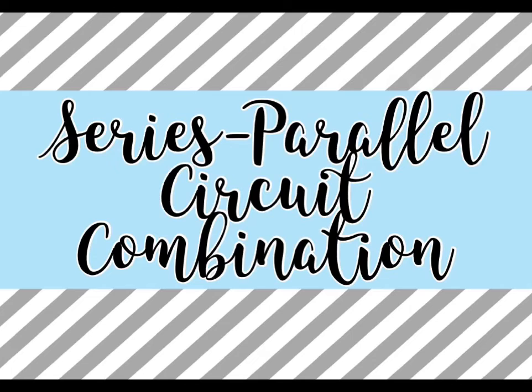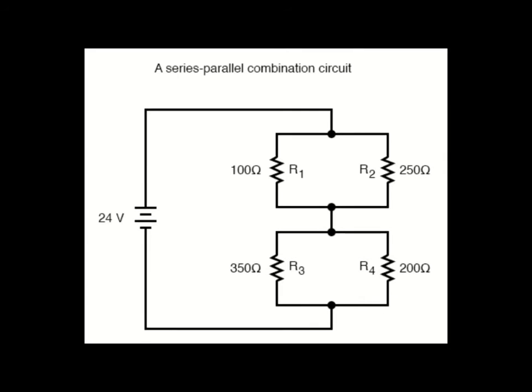A circuit with a combination of series and parallel connections. One example is the switch that is in series with the respective devices, and the devices are in parallel with one another. Switches are variable resistances. When they are closed, the resistance is negligible, and when they are open, the resistance is essentially infinite.